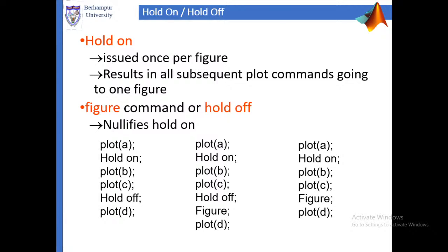Now hold on and hold off, this we have discussed earlier. What is done is, hold on you have to issue once per figure. In one figure you cannot use hold on multiple number of times. So this is something that we left last class. I am stressing this, that please use hold on once per figure. The result is that all subsequent plot commands are going to be in one figure only.